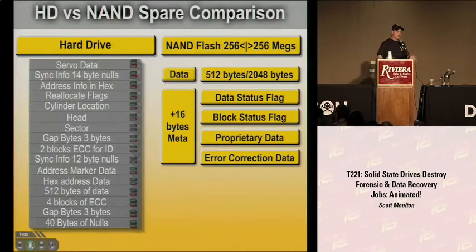And this was kind of smart, actually. Basically, what they did was they said, well, we never stored anything in the cell that's actually at this particular number, which is like 517 bytes into the disk or something like that, where the block status flag is. No cell there has ever been used, and physically it still sits there as an open cell. And if I want to say it's bad, the only thing you have to do is write an electron into it, and then bam, you're done. It's now marked as a bad sector. So at least from that standpoint, you've actually got a bad block right off the bat.